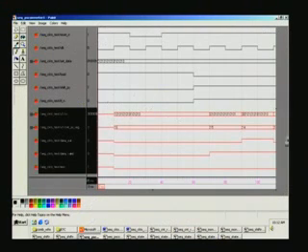So here, as usual, a reset is applied, and this is set data. Here also we are setting the same 1010 pattern, and a shift register. What happens? Internally there's a 16-bit shift register, and that is preset to the same 1010 because that's what we want, and at the positive edge of the clock because the code has been written like that.